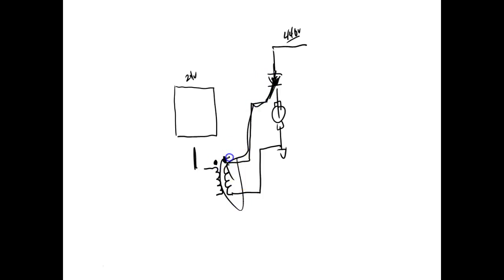It's going to burn up your pulse transformer, and you replace that pulse transformer for almost nothing, but you don't mess up your $2,000 PLC. So normally when we fire these things in a high energy circuit, we fire it through something, and we can also fire it through an optical isolator.